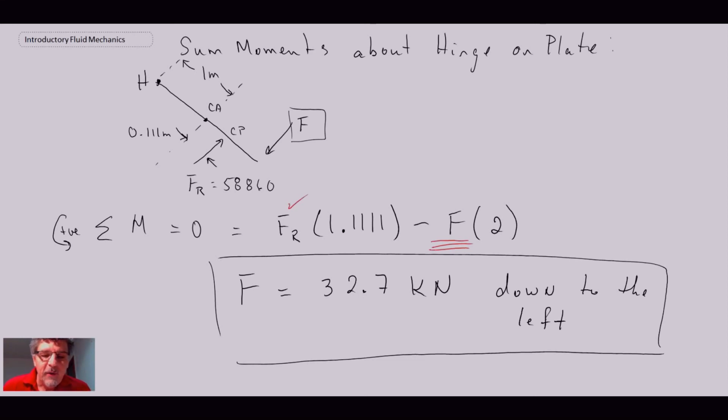But it should be pretty intuitive. You have to push it down in order to keep that plate from opening up due to the hydrostatic pressure on the other side. So that is an example problem of using the forces on a planar surface. We've used the forces, we've used determining where the center of pressure is, and we found that it's different than the center of area. And it gives you an example of how to apply it.